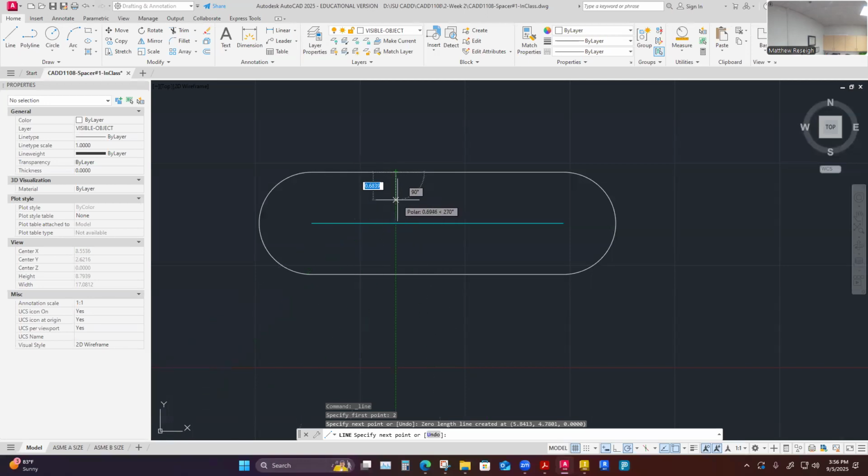And orthographic mode on the status bar is this little right angle thing. It allows you to stay in horizontal and vertical alignment, right? So F8. This is a good reason why I might say I need this to be a half inch down, perfectly straight up and down. I'm there with that green tracking. It looks pretty good. I can see the 90 degrees. There's a lot of references here that I don't need.